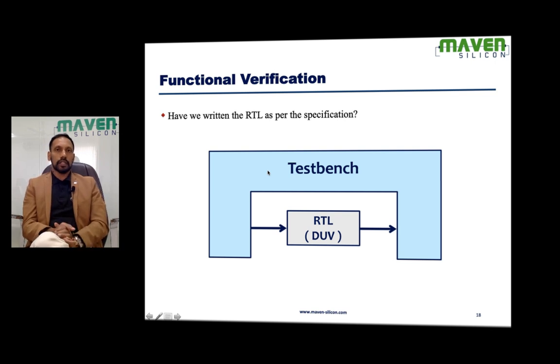Think of simulation debugging. During simulation, the simulation stops because there is a data mismatch. Then you look at the waveform. Okay, here, this is the place where the data mismatch happens. Then you might need to identify the cause. That's the most important thing.